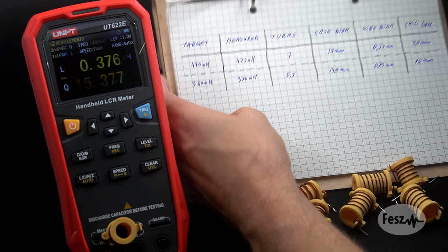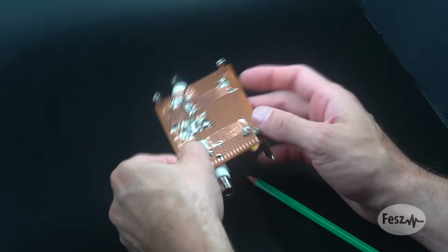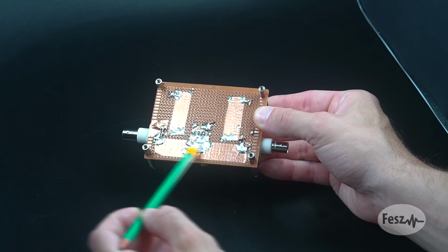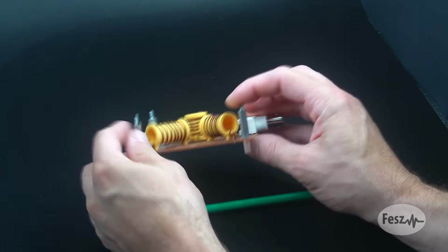Now, I was not very sure of how well the circuit would work, so before going for a proper board, I tried building the filter on a perf board, and used some copper tape to make wide, low-loss traces. So all of the large components, the connectors and inductors, are placed on one side, and the small SMD ceramics on the other. An important thing to mention here is that the coils are placed at right angles, one in reference to the other, and this is deliberately done to minimize coupling in between them.